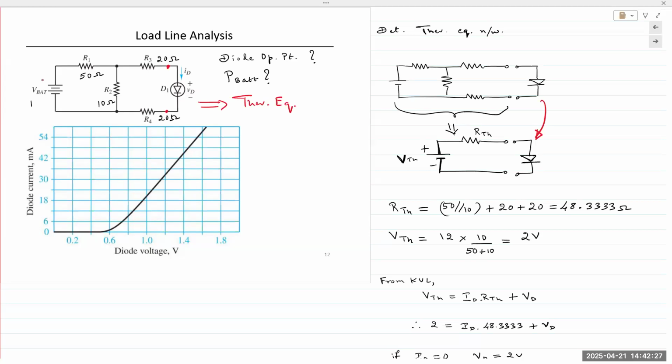Okay, so if you want to determine the Thevenin circuit for a component, we have to remove that component from our analysis, which we do here. That leaves behind open terminals, and we analyze the circuit between those open terminals, A and B.